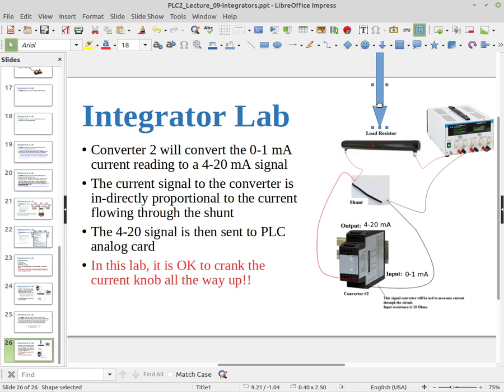So you want to be careful in the classroom. If you touch this resistor after you've been putting 3 or 4 amps through it for a while, it's going to get hot and you might burn yourself. So don't leave it at 3 to 4 amps for a long time. Turn your current knob down and restrict the current while you're working, and you can adjust it periodically when we're trying to mimic power being used in a house, turning something on and then turning it back off.